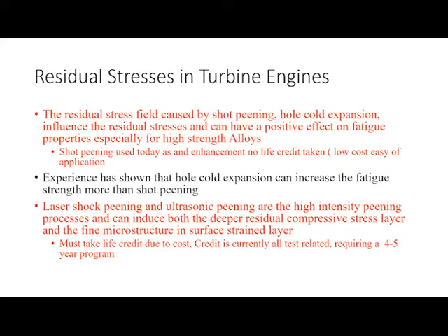And the one thing we have figured out is when we do want to take some kind of an enhancement on fatigue strength, cold working a hole, like a bolt hole in a disc in particular, does provide greater potential than shot peening. And we do have discs that fly today that are cold hole worked, but we go through a very extensive test program and kind of limited